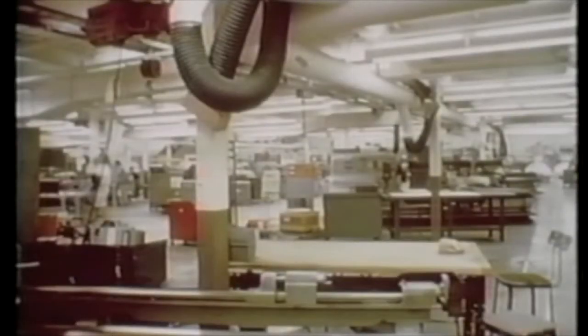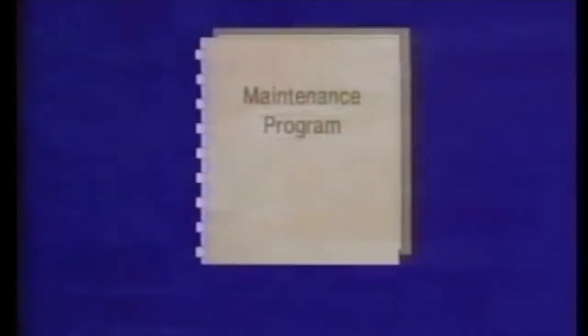If employees complain about the hood or refuse to use it, check to see if the hood interferes with work, or perhaps the hood just doesn't do the job of providing good emission control. All ventilation systems require maintenance. A good maintenance program consists of, first, a written program, second, a good record-keeping system to store drawings, plans, specifications, modifications, operating instructions, monitoring and testing results, and so forth. Third, a good program provides for regular testing and inspection of the system. Checklists can help. One is provided in the handout materials included with this program.